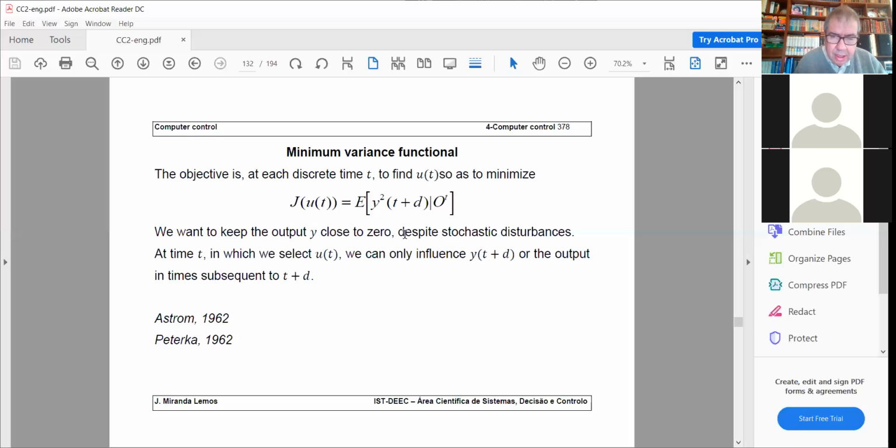But I can mention to you, if you try to solve adaptive control you put together online identification and control. So you are identifying your system whenever you receive new data online. Instead of having a batch of data obtained from experiments, you get a model and then you design a controller.